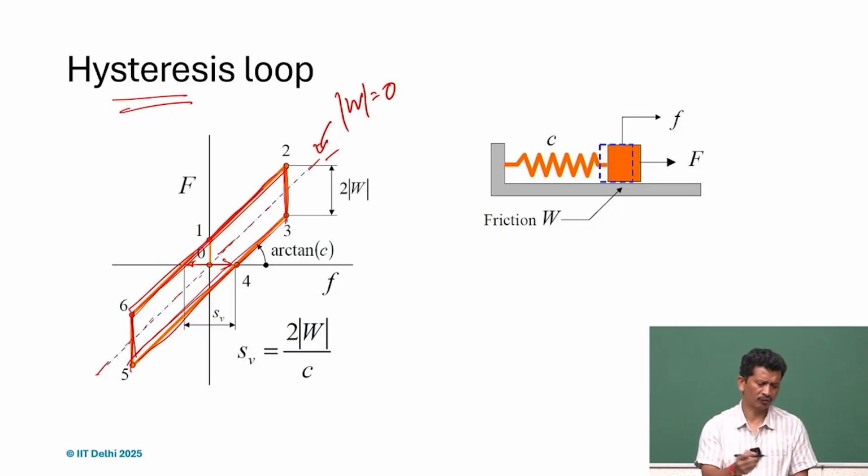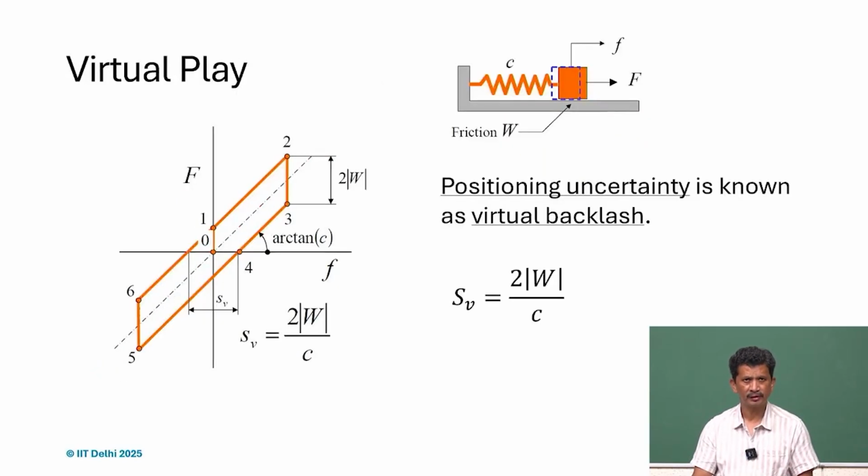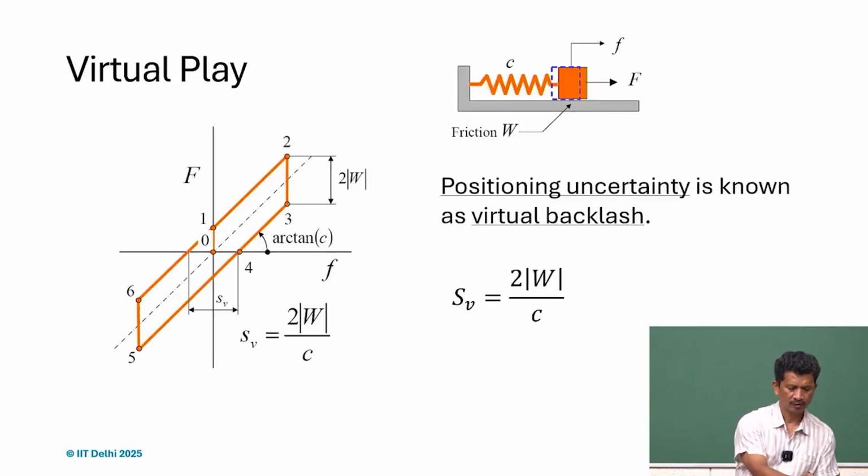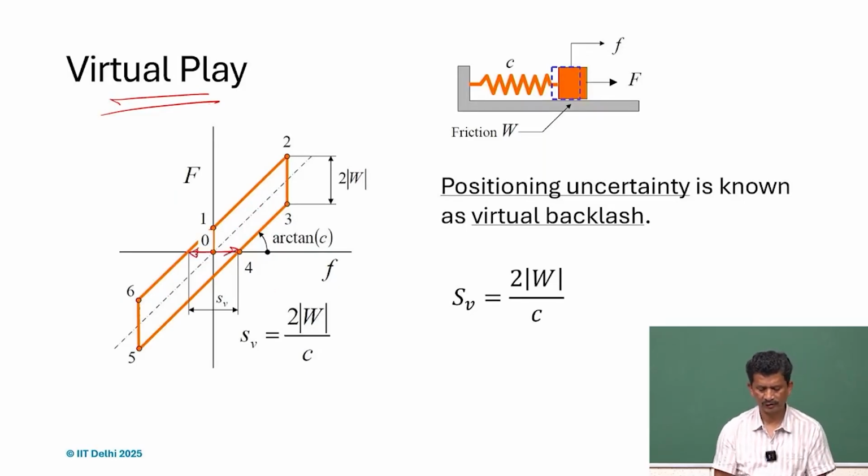So it means it's quite repeatable, right? The force versus displacement is linear and the C is the stiffness. So by some means, if it's floating and there is no contact between the frame and the body, we realize that it's repeatable, there is no hysteresis kind of thing. And that's why every time we talk about precision, we also talk about friction. So this is the hysteresis, and the associated uncertainty is what we just explained.